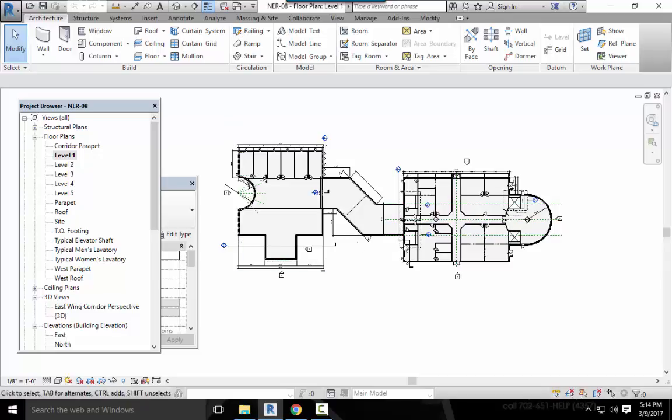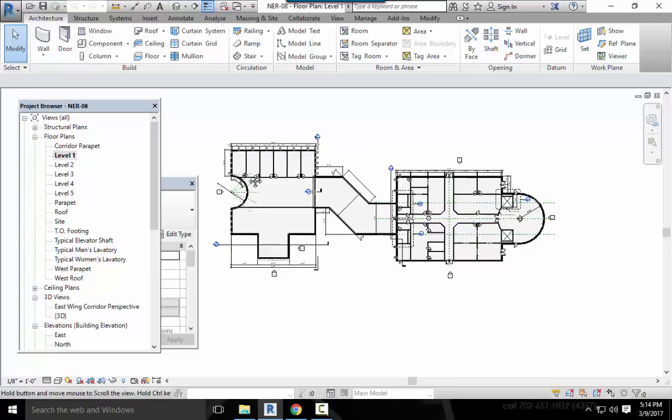So the first thing the contractor typically does once they've got the grading done and the building pad set is they set the corners of the building and they string the grids. Then everything else comes off those grids. The underground plumbing, the walls, so you can really think of those grids as a fixed element that really helps not only through construction but in design as well.